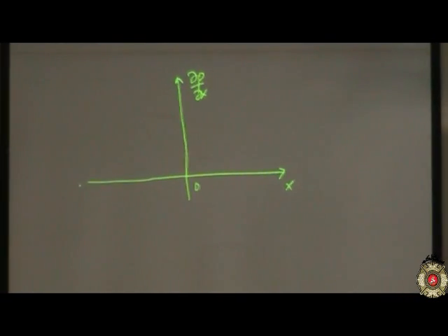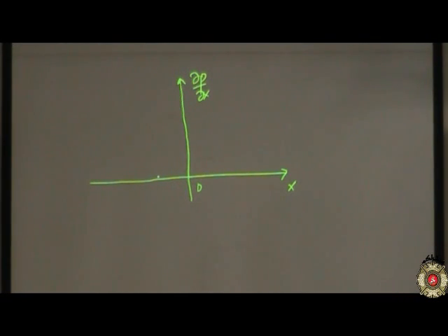Since we are analyzing only in this direction, which is, let's say, minus A, the cylinder is somewhere here. So you will see that the pressure is something like this. Suddenly it goes up and then drops to this. By the way, it drops straight, but look at the book, it has a better figure. I could not draw it well. So the point here is there is a peak pressure just before it drops down to 0.